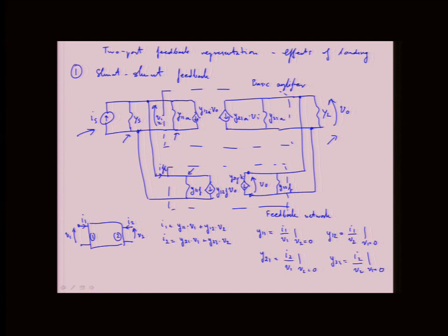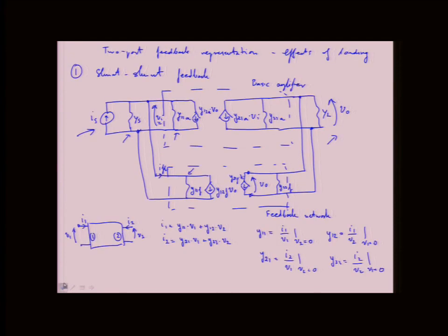The other part we need is the current from these controlled sources. We write that as Y12A plus Y12F, the one from the feedback, times Vout. That's the reverse signal flow that impacts the input current from the output voltage, both through the amplifier and through the feedback.